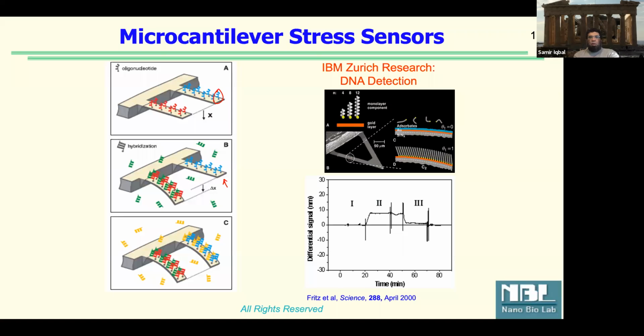So that's one example. We would see bending, right? Now, bending can be detected in many ways. Maybe we are looking at the resonance frequency, and when the weight changes, the resonant frequency would change. That's one phenomenon, resonant frequency. We know everything in nature resonates at some specific natural frequency. That natural frequency can change if the property of that material changes.